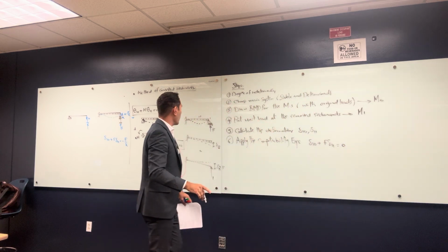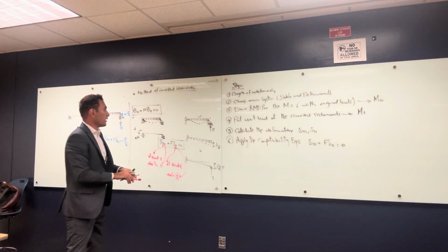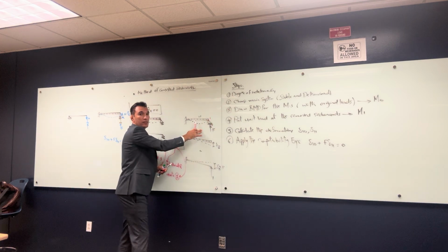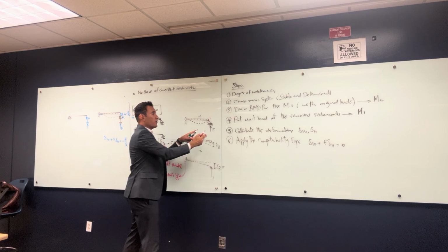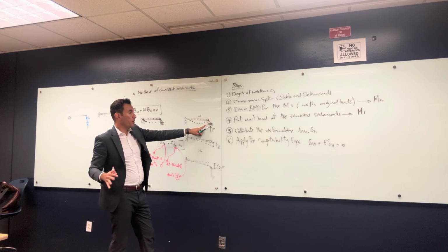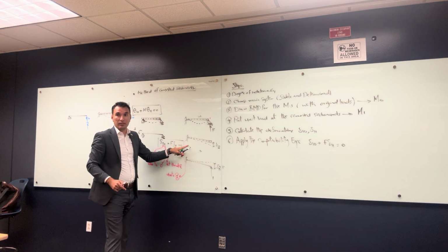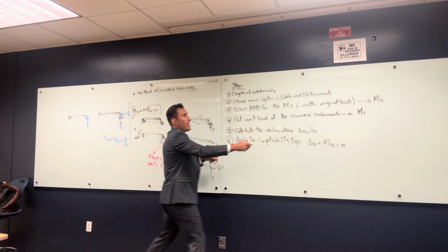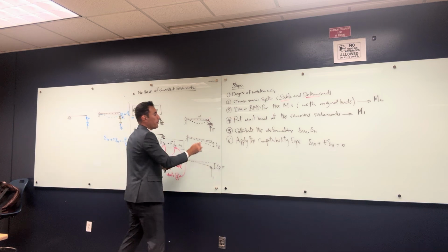And at the end, if we want to draw the final bending moment diagram, you're going to have a bending moment diagram from this beam. Like, let's say, okay, let's go through step by step. Degrees of indeterminacy. I know that this beam has one redundant, right? It's 1 degree indeterminate. So that's the first thing that I decided. And I decided to choose this as a redundant. I'm gonna remove the support. So I did number one, choose a main system. I choose the cantilever as a main system. I remove the redundant and I choose a main system that is stable and determinate.